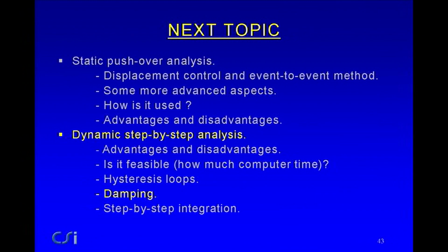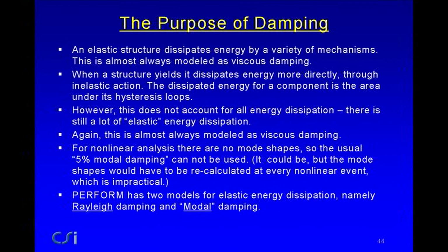Let's look at damping. Damping in dynamic analysis is a tough issue. Firstly, let's look at the purpose. An elastic structure doesn't lose energy. It's elastic. Any energy you put into it is stored as strain energy. It can come back out again.